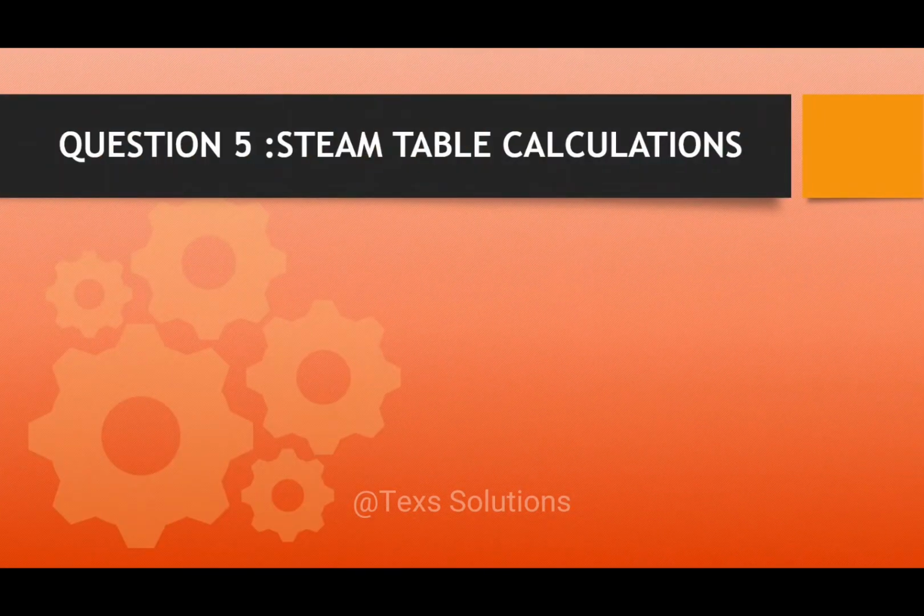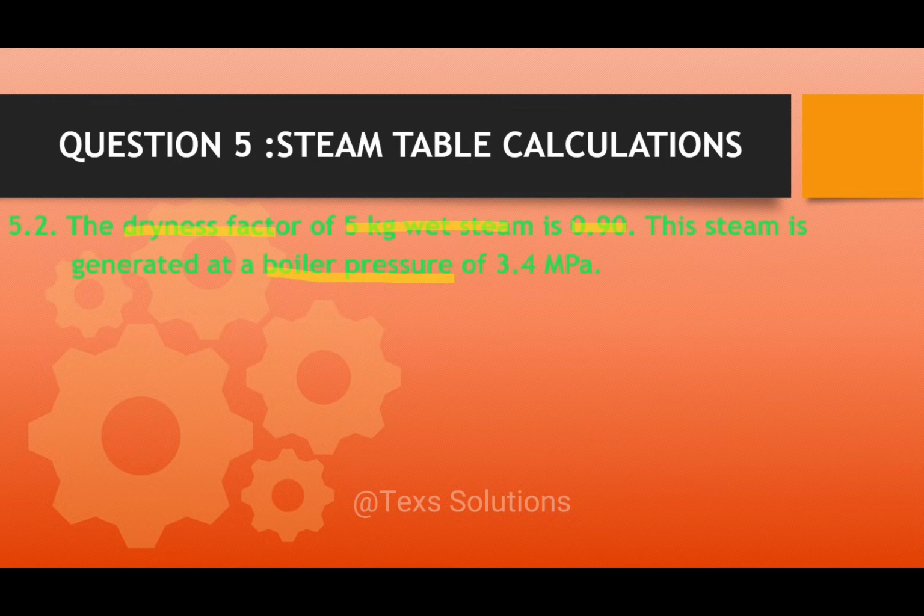Let's go to question 5.2, and this now deals with a new section in heat. We are now going to be looking at steam table calculations and how to calculate the heat energy for the different types of steam that is being produced. So question 5.2 reads that the dryness factor of 5 kilograms of wet steam is 0.90. Wet steam is steam that simply has water particles in it, right? This steam is generated at a boiler pressure of 3.4 megapascals.